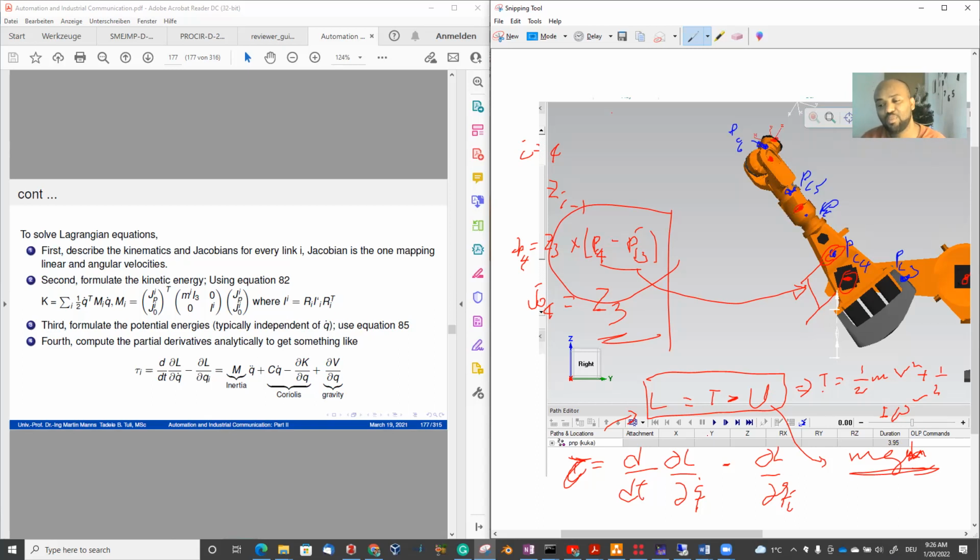But this time, there is a possibility that the robot could go to a singularity configuration. If this singularity configuration happens, you have to solve it by constraining the joints and repositioning the robot, or, if that's not possible, the operational space, where you have to do the work. This is actually where you have to do it.